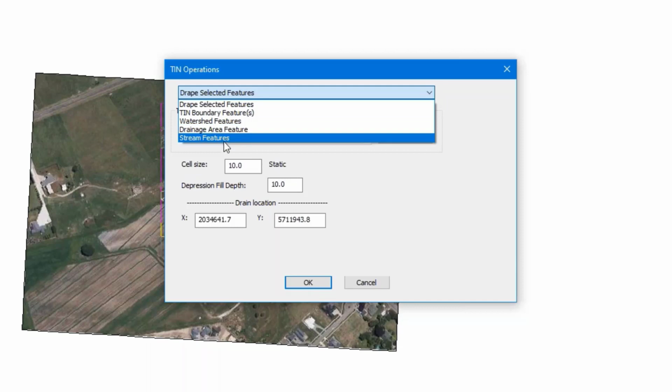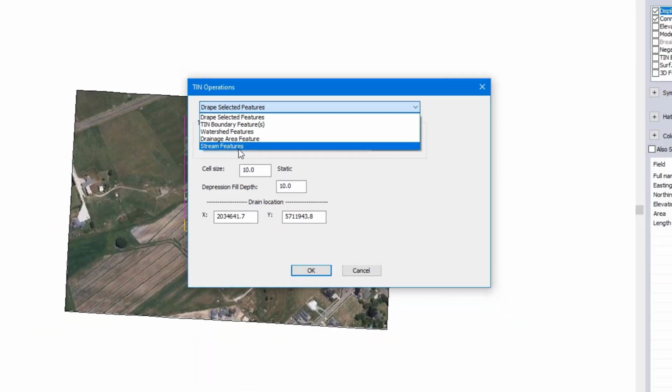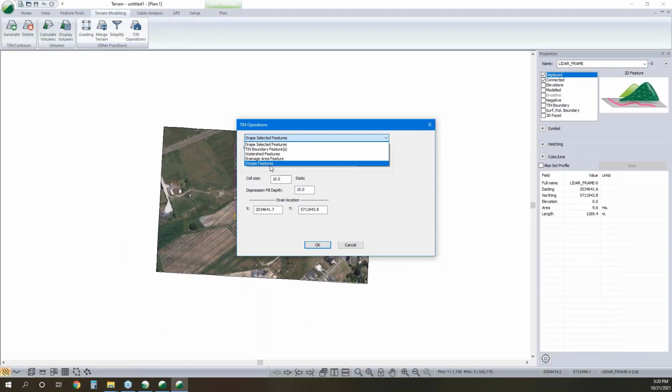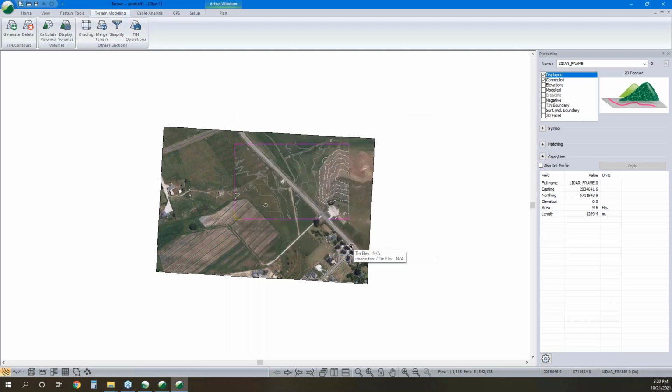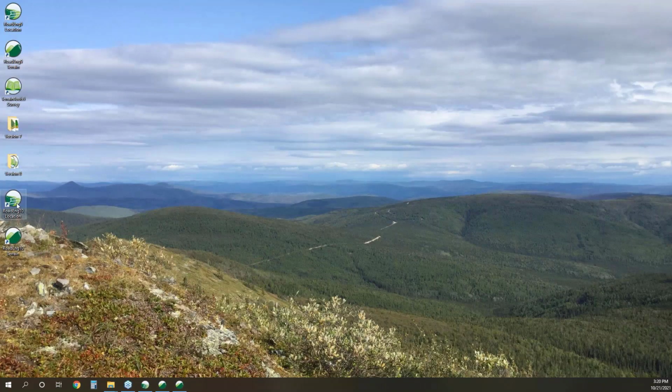And we've got a streams feature tool in there that'll help predict flow paths given a minimum catchment area, and also model ponds where water is expected to stand. So both useful for planning culverts and road locations. Now let's jump into location.